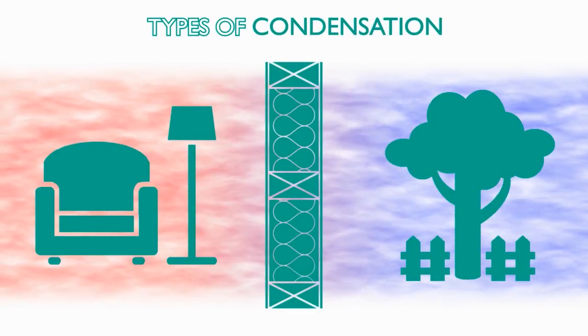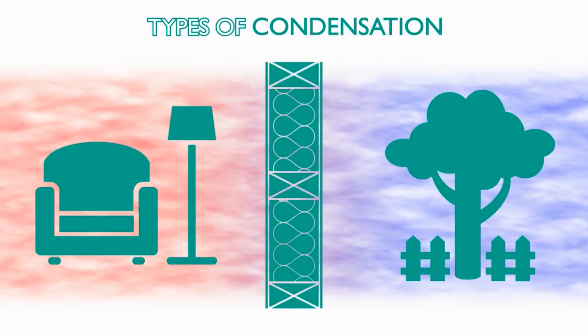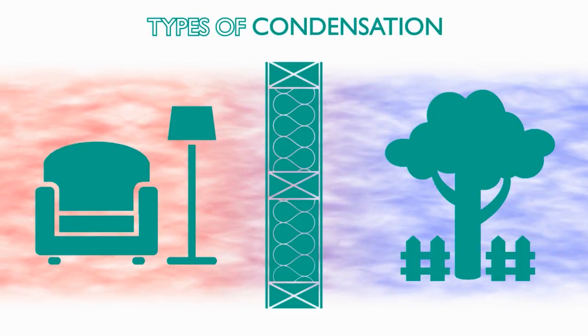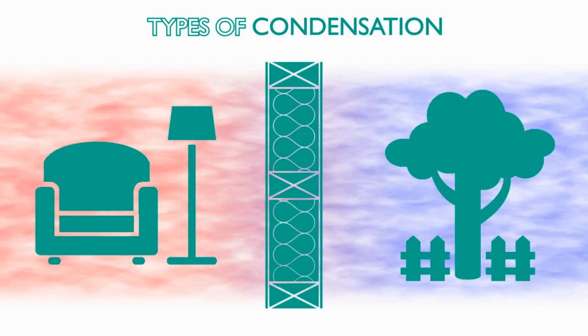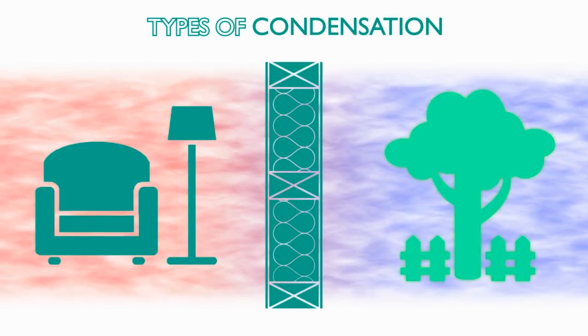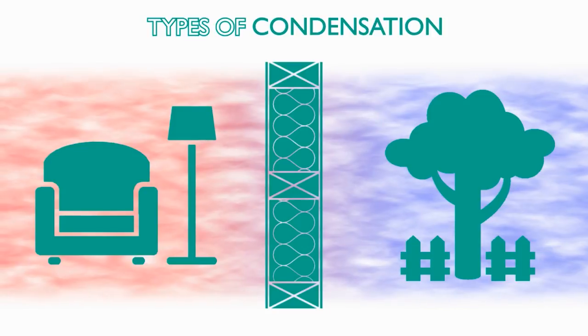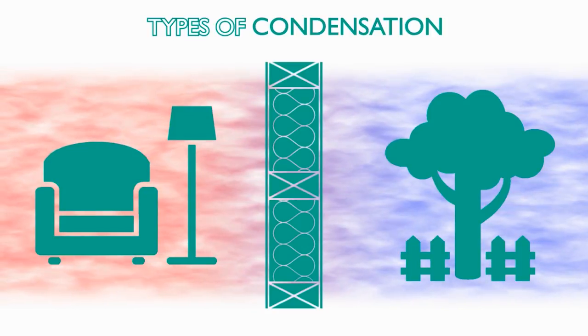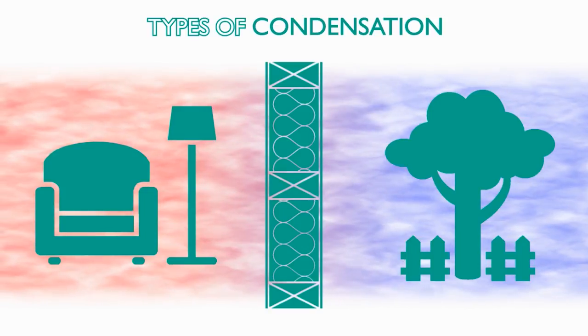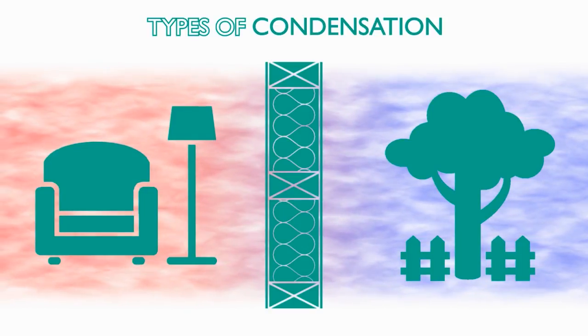In the habitable areas of buildings, warm, humid internal air creates what's known as vapour pressure. Vapour pressure is the driving force behind condensation risks in buildings. In the UK, this process works from inside to outside, pushing the moisture into the walls, floor and roof of a building, towards typically cooler and less humid conditions outside. So how does this vapour pressure give rise to a condensation risk?